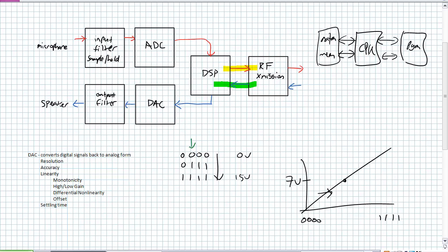As I said earlier, you expect there to be an equal range. Think about perhaps there's a high gain at the high end or low gain at the high end. Be aware of some of those errors that can occur there. We want that linear approach. In addition to those gains, there's also what's called the differential nonlinearity. Perhaps we're doing fine here, and then all of a sudden we start tapering off inaccuracies at the higher end of that range. Very similar to some of the nonlinearities there. It's still linear, but could you imagine perhaps an offset? I'm trying to draw that parallel where 0, 0 accidentally is being represented as 6 volts, or perhaps a negative offset. Those are undesirable characteristics.